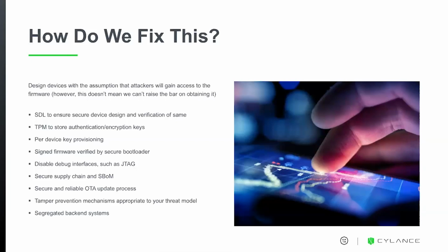Tamper prevention mechanisms are good, appropriate to your threat model. So if you're utilizing a high security device, it may make sense to use things like case switches, epoxy over critical components, et cetera. This might not be appropriate to a consumer device because, again, it's not appropriate to your threat model. But they are useful in the right context.